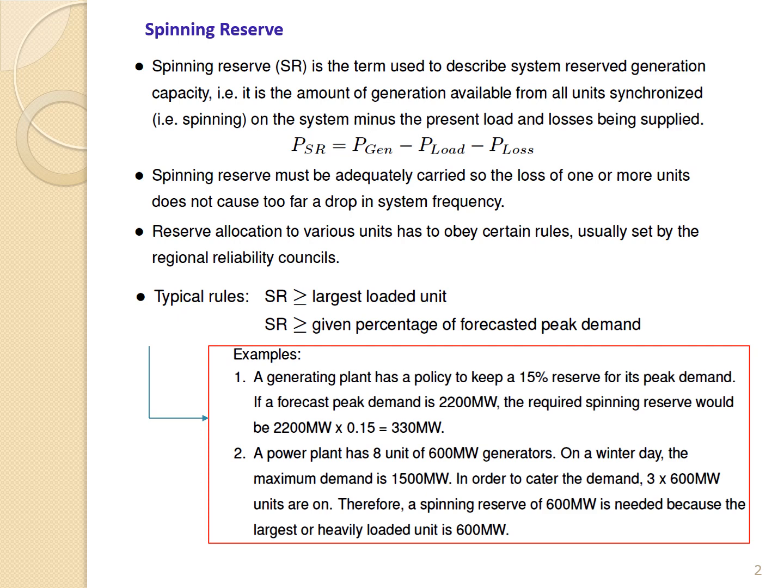The meaning of extra margin or extra generation capacity available is this: suppose a generating unit is supplying a given load and is already connected into the network. Suppose its maximum capacity is 100 megawatt and it is currently supplying a load of 90 megawatt. So we have a difference of 10 megawatts available with this particular unit, which means the margin or the extra generation capacity of 10 megawatt is available with this generating unit.